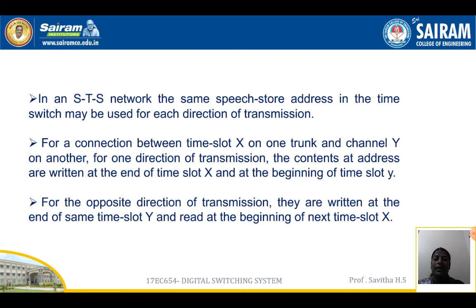In an STS network, the same speech store address in the time switch may be used for each direction of transmission. For a connection between time slot X on one trunk and channel Y on another, for one direction of transmission, the contents at the address are written at the end of time slot X and read at the beginning of time slot Y. For the opposite direction of transmission, they are written at the end of the same time slot Y and read at the beginning of the next time slot X.